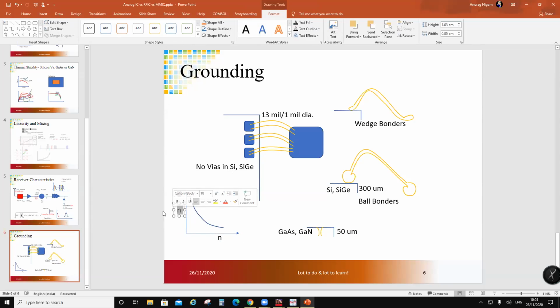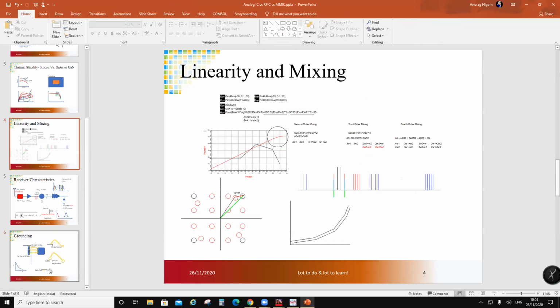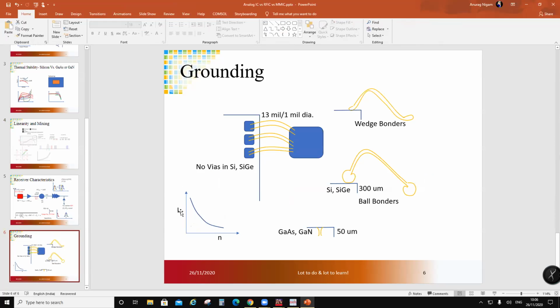Okay, so this is self-inductance plus the mutual inductance. And this inductance keeps dropping as I increase n, and beyond 9, no matter what angles you do. So basically, you can always do these wires at angles. When you do these wires at angles, the inductance goes down, because the mutual inductance goes down.